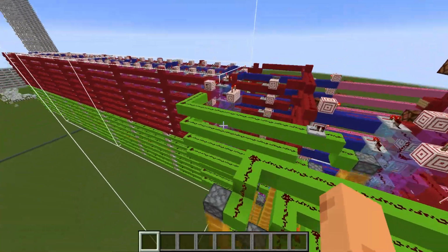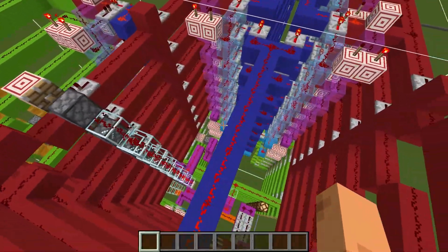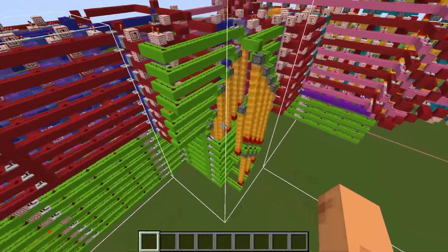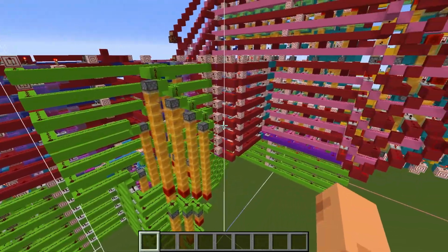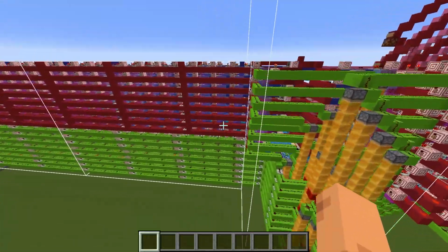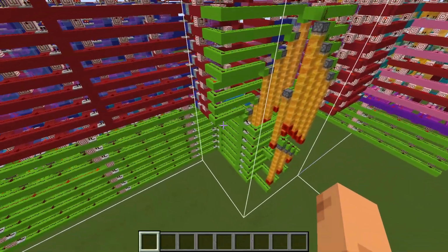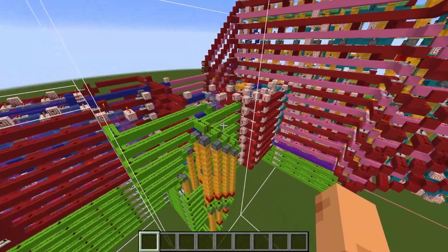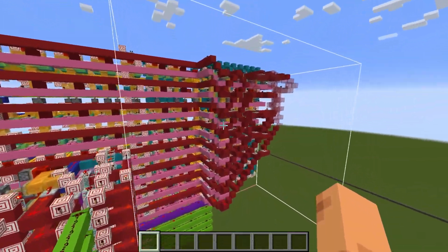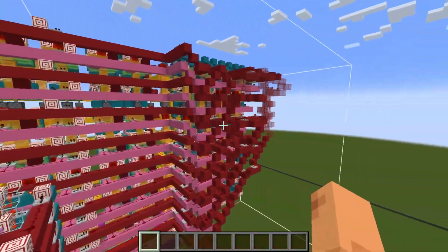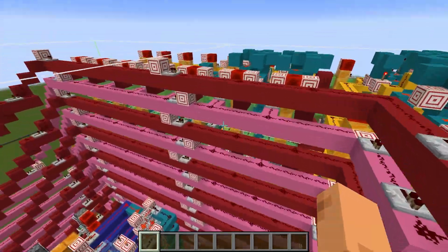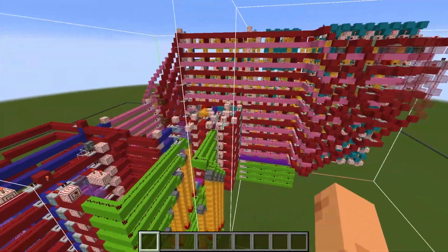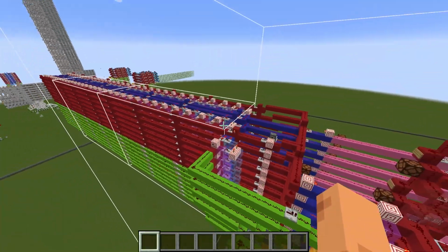So this is actually something specific to this architecture that I've used here, is that the instructions are always 2 bytes in length. It's a fixed instruction width. And the first byte is basically the opcode that determines which ALU operation will be enabled. And the second byte is the instruction-dependent data associated with it.